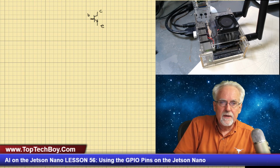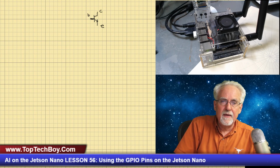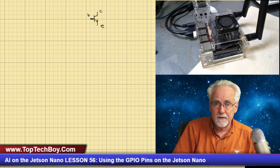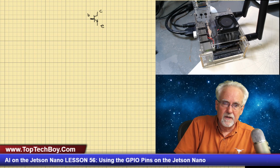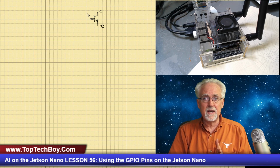And so one way to think about this is an on-off switch. If you put 0 volts on the base, you won't get any current between the collector and the emitter. If you put a voltage on the base, you turn it on, and then current will flow from the collector through the transistor and out the emitter. So you can look at it as a switch.